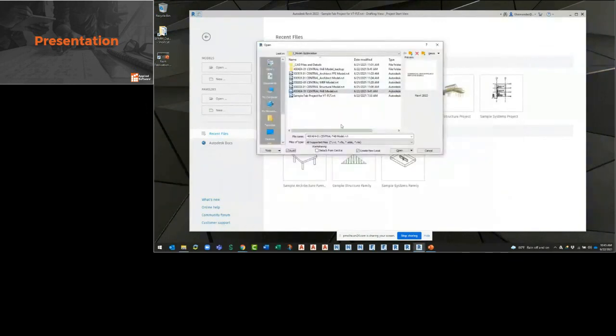Okay. And then, of course, the other thing that I want you to see was this here that I recently talked to with some of our other clients, and they really thought this was awesome and didn't know that that was there. That little black arrow, when you're working with a central file, look at this real quick. This is just a training file here, right? And if I go to the black arrow, it doesn't do anything. But when I'm in a central file, creating a local file situation, you can use this little black arrow. This is what we call demand loading, right? So this again is for optimizing performance in a model.